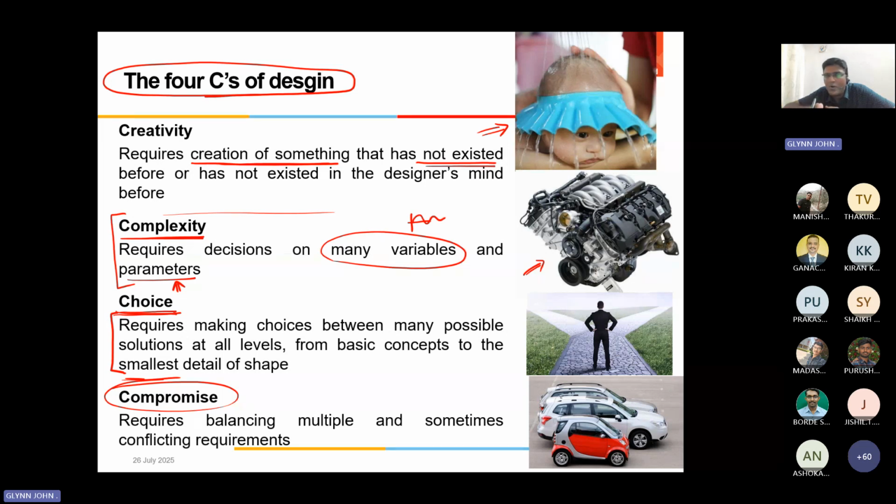So now if you look at the modern motorcycles or cars, they have a lot of plastic parts. Wherever strength is not very critical, or lower strength will not cause any major damage, at that point they choose plastic, right? Where strength is critical, they choose metal. They use a combination of both. For example, mud guards of motorcycles are made of plastic nowadays, right? Because even if they break, nothing is going to happen. But the body, the chassis, is made of metal, right? In some cases, even fuel tanks are made of plastic, because even if you strike it with some object, it's simply going to deflect, it's not going to break, right?